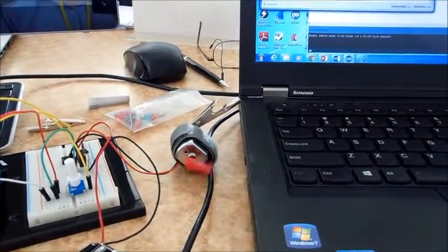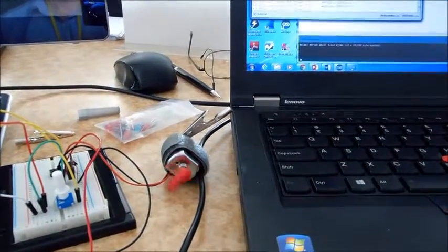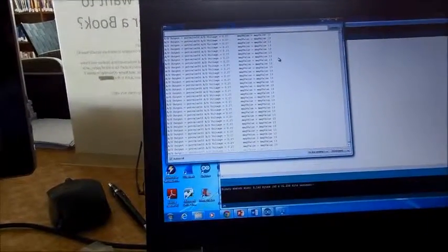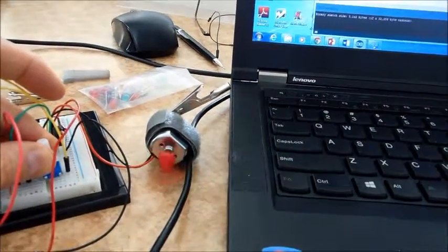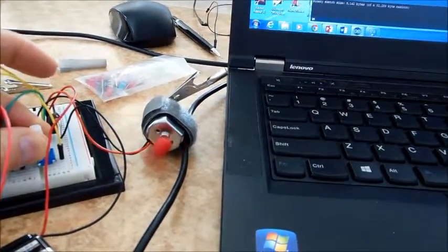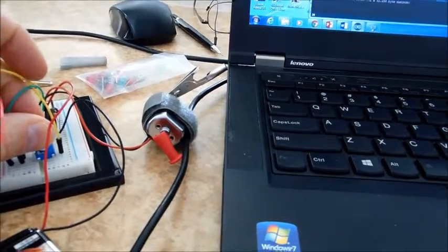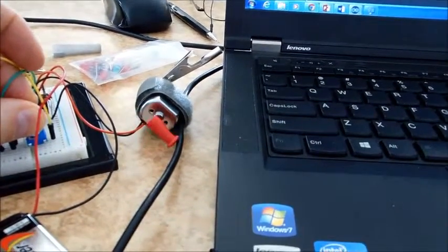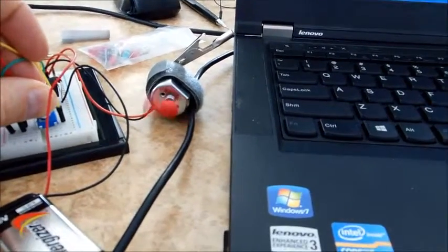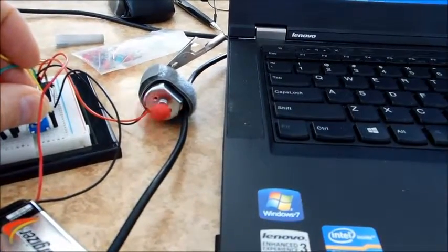And so what we've got over here is a pot, and you can see that the motor does rotate a little bit. Right now, that's about a quarter volt that we have on the motor. So it starts running at a quarter volt. And if we adjust it, there, we're about 0.37. There we just went down and we stopped the motor, but we can see what happens when we start getting it going. That's about 0.4 of an amp.